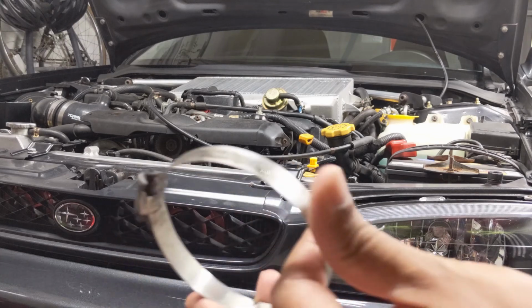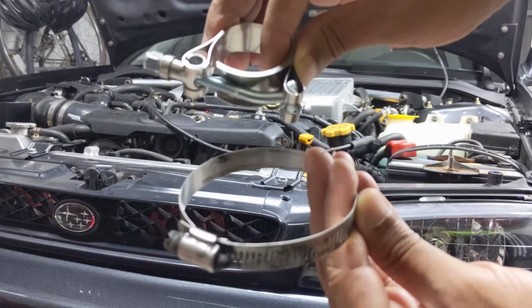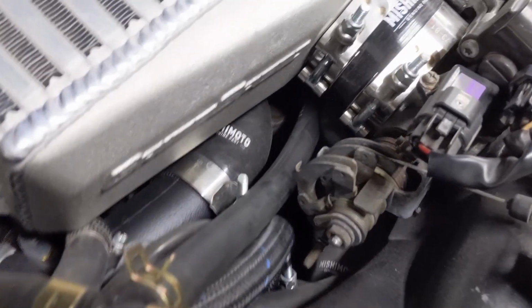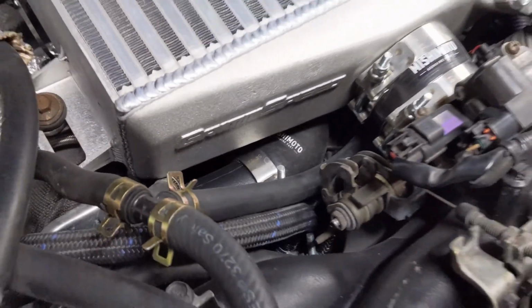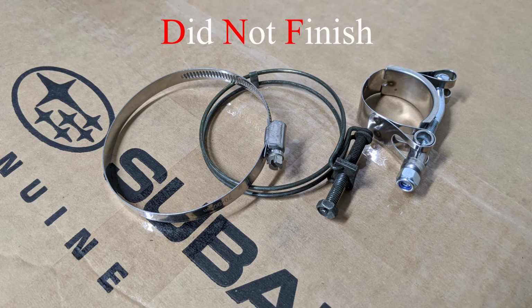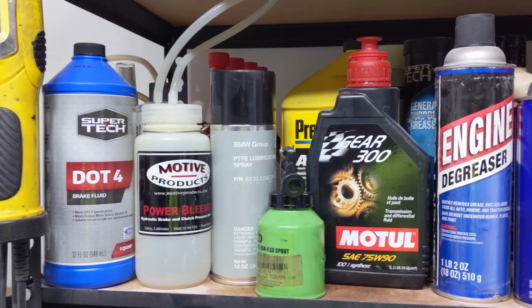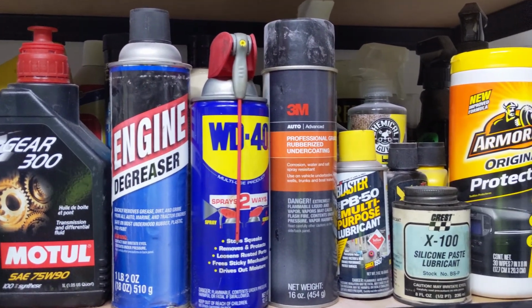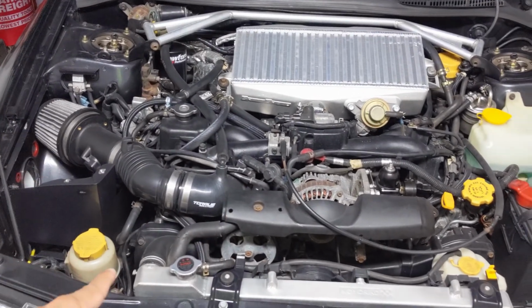The clamps used to hold the hoses are just as important as the hoses. As your power increases, the need for stronger and reliable fittings will increase across the board. As you can probably imagine, it's the most obvious when concerning the forced induction components. Save yourself the frustration and embarrassment of being stuck on the side of the road or a DNF on race day by getting quality clamps, and make sure all the tubing is clean when you install it. And just like a completely stock vehicle, you want to check and inspect your maintenance items on a regular basis. You don't necessarily have to do it every week, but while you're doing oil changes or maintaining something else, and especially when you're going to an event, take your time and look over the vehicle.